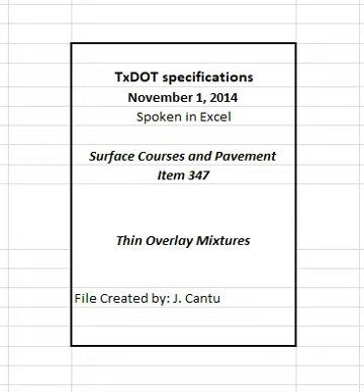3. Only applies to mixture produced for Lot 1 and higher. 4. Binder content is not allowed to be outside the limits shown in Table 6. May be obtained from asphalt meter readouts. 5. Test and verify that Table 7 requirements are met.